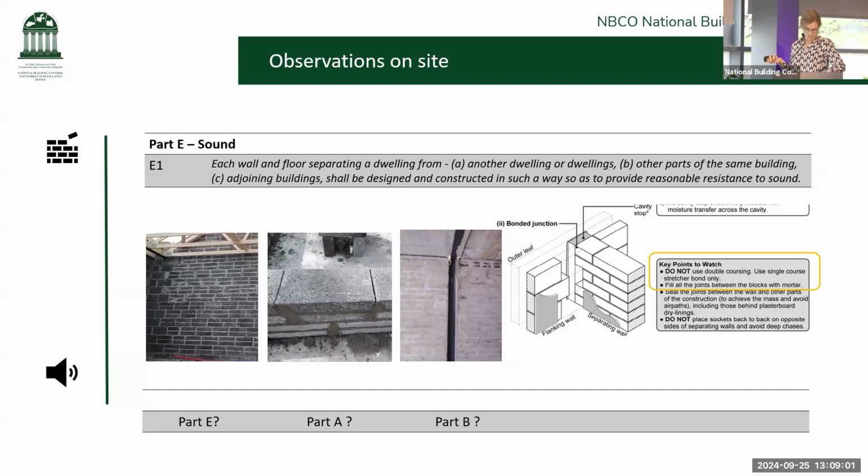So in walls of double course blockwork, additional sound testing may be requested to demonstrate compliance, and again may comply. Hopefully it's not too late if you get your results and they don't comply. So following the technical guidance is prima facie compliance.